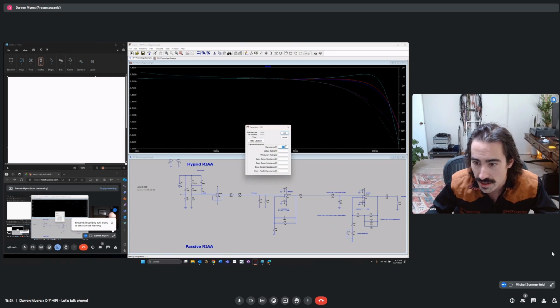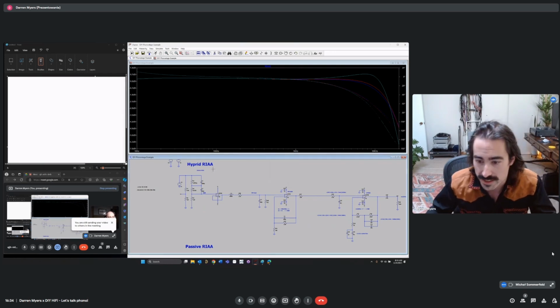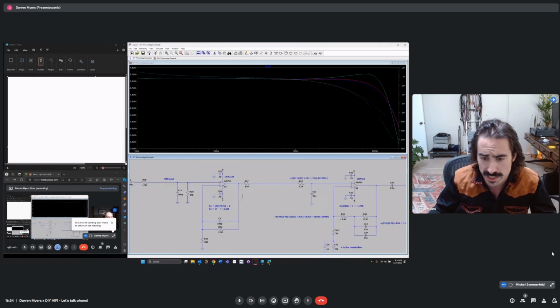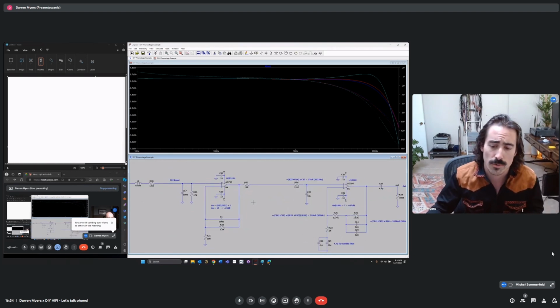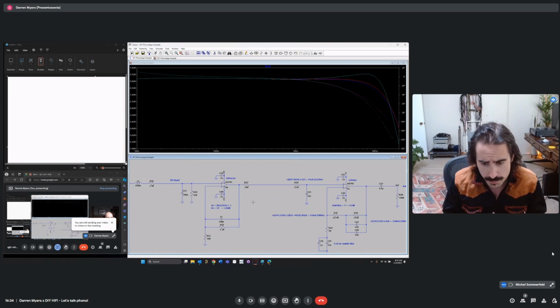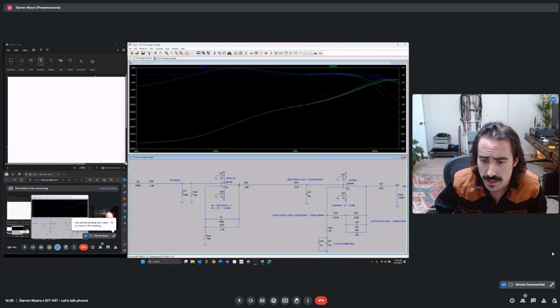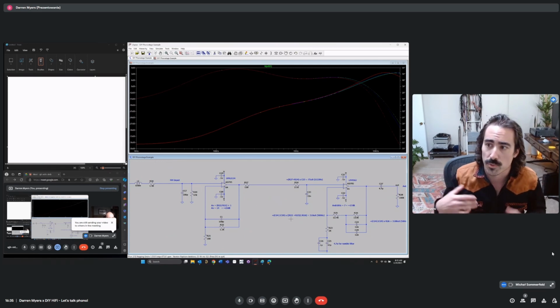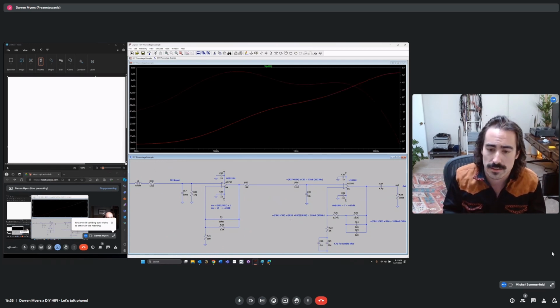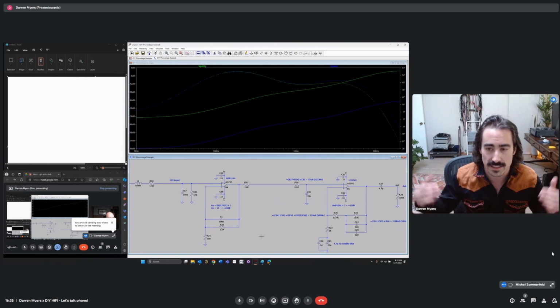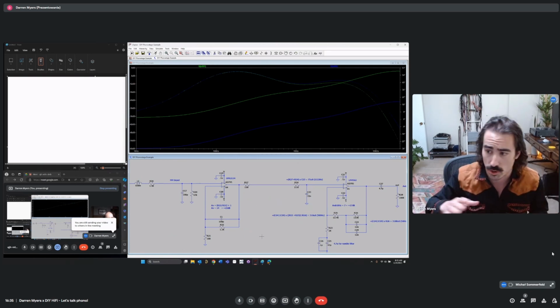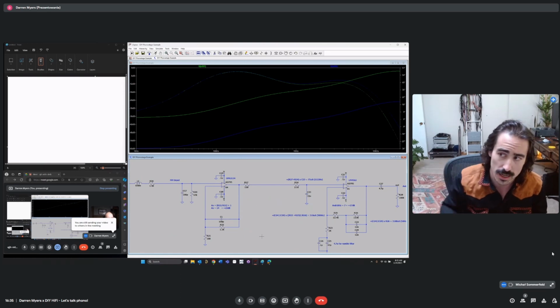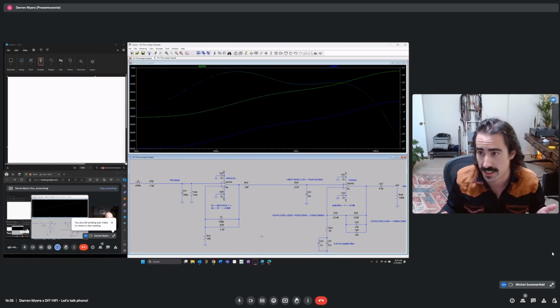Okay, so now that we've discussed that, I think we understand why we need those components. Let's go over to our first amplification stage. What we want to do is apply some gain to the entire signal. So if we look at, well, now I have to run this. So if we look at the output of this relative to the input of this stage, you can see that what we've done is we've applied widespread, wide bandwidth gain to the signal, but we haven't corrected any frequency element.